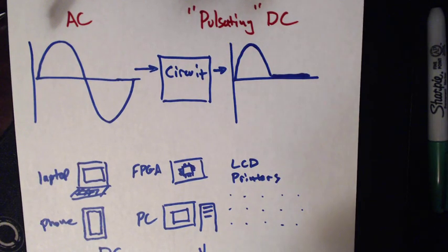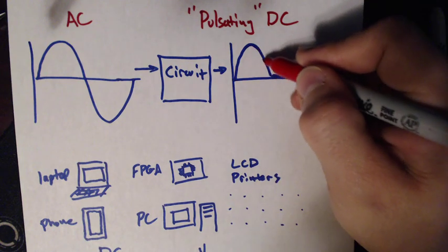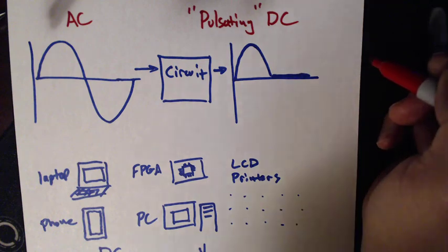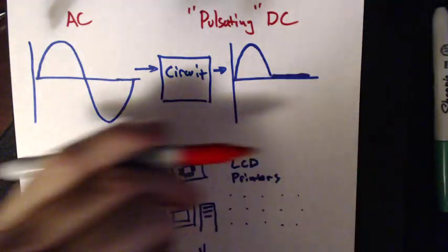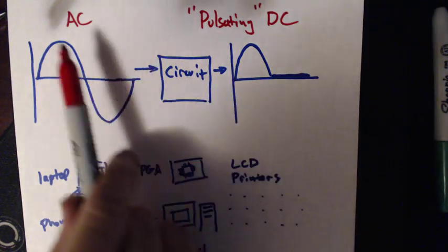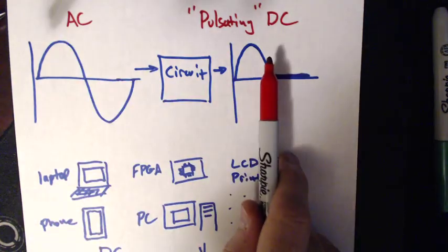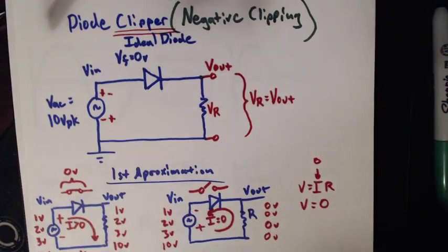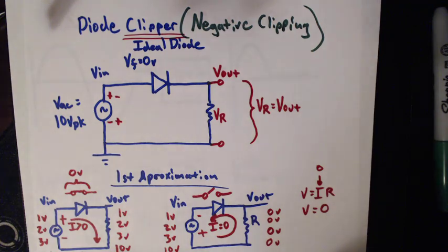It's direct current. The electrons are all being pushed in one direction. Positive, no push, positive, no push. And the electrons are all going in one direction. So at least we've done one thing right here when we're talking about converting AC to DC. So this very simple circuit is the beginnings of every single modern power supply that we use in every single